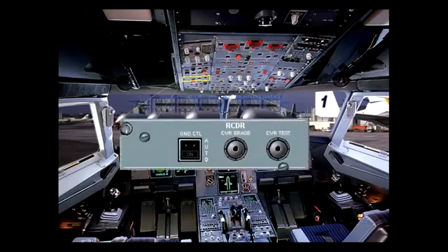The cockpit voice recorder, CVR, is used to record all the communications and oral warnings in the cockpit. PA announcements are also recorded, provided at least one PA reception knob is selected on. The last 2 hours of the recording are retained.